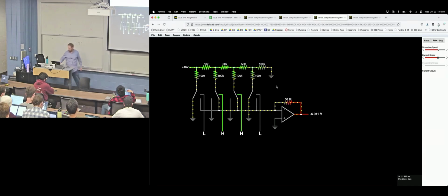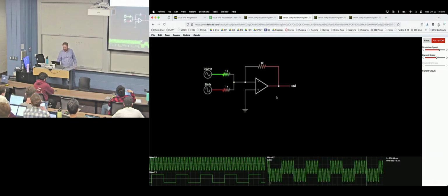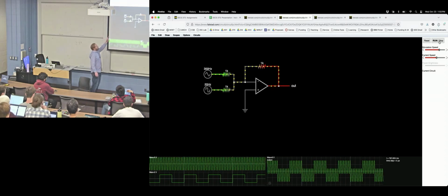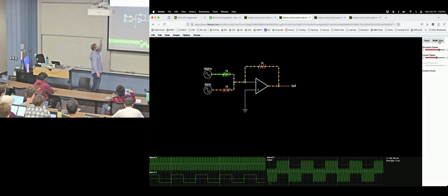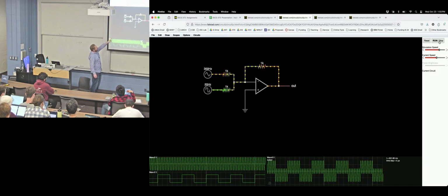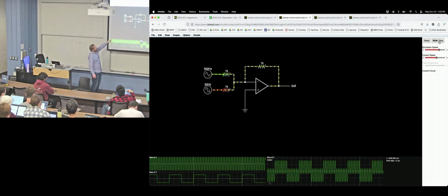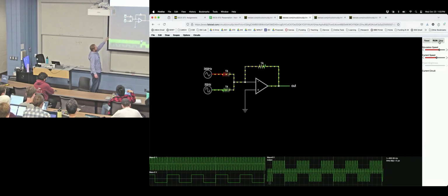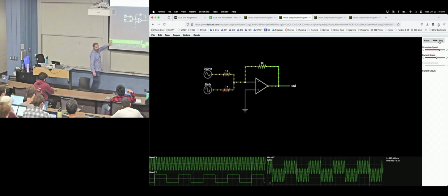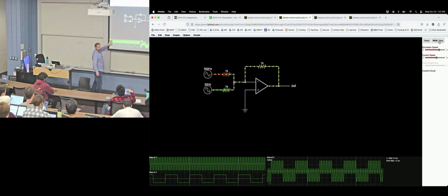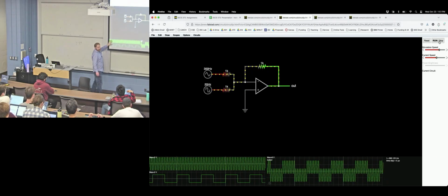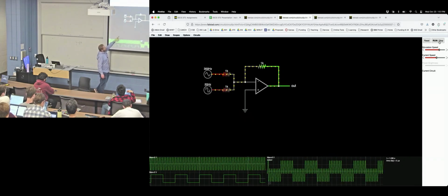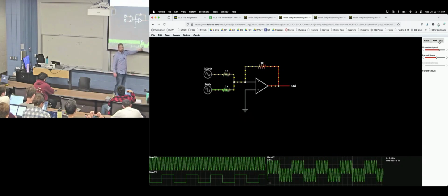What's the difference between smooth and square waves? So there are two different signals. We have a 300 hertz sine wave on the top that is going into the negative node on the op amp, right through that resistor. So you got a summing node, and then we had a square wave. So these are the two signals. Do you agree? That's the difference between those two? So sine wave here, square wave here, both going into that node. This is the output.